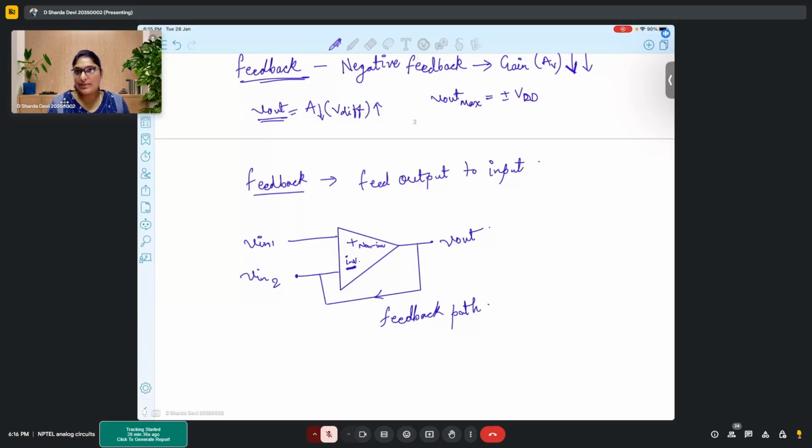That is inverting behavior. In non-inverting behavior, the moment you give an input to the non-inverting terminal, your output will be positive, or in the same phase as that of the input. So that is what is meant by the non-inverting terminal. Also from the names themselves, you can understand: inverting means something that flips, so 180 degree is a flip, and non-inverting means nothing happens, so 0 degree phase shift.